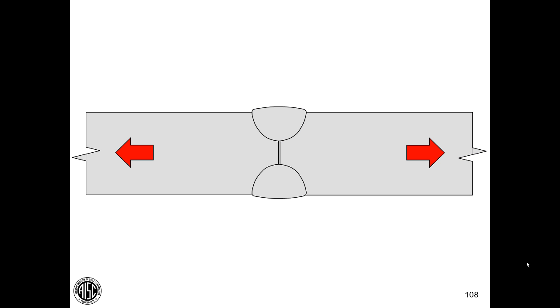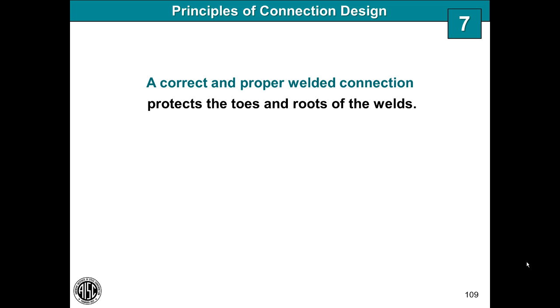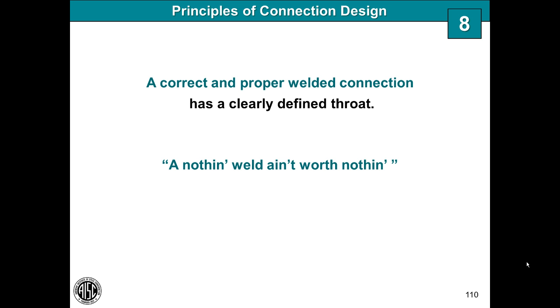Watch your toes. Remember your roots. That's number 7. Number 8. A correct and proper welded connection has a clearly defined throat. A clearly defined throat. And my little saying, a nothing weld ain't worth nothing. Now that begs for a definition of what I mean by a nothing weld. And so here it is. A nothing weld is a weld that looks like what you wanted, but it ain't.